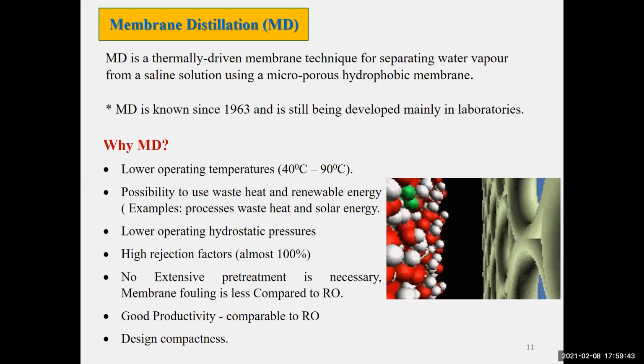That's something we have done before. I may have mentioned that in one of the experiments we used the heat of the exhaust of a car to heat the seawater and run a membrane distillation system. Solar energy is definitely something we have tried earlier. We have built solar units that desalinate water through this technology, membrane distillation. You can use energy rejected from the condenser of an air conditioning system. Anything that has low-grade energy rejected is good enough to operate a membrane distillation unit.